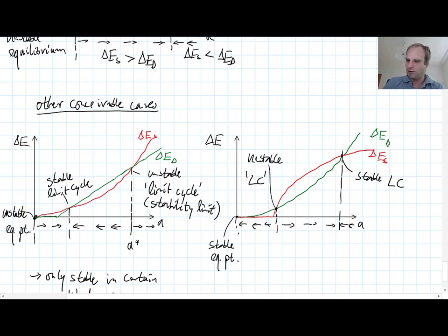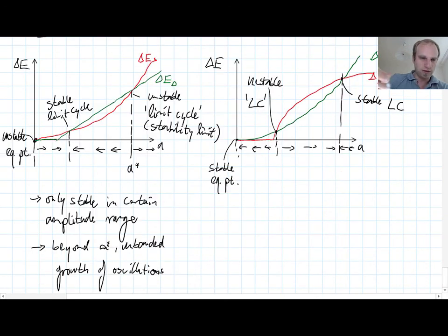And I mean the lengths of these sections could be arbitrary, right? This threshold here, beyond which we reach this stable limit cycle, could be very, very small, could be very close to the equilibrium point. So linear theory predicts stable behavior, but actually the threshold is very small until which we reach a perhaps very large amplitude limit cycle. So this is also an interesting characteristic behavior that we may get.